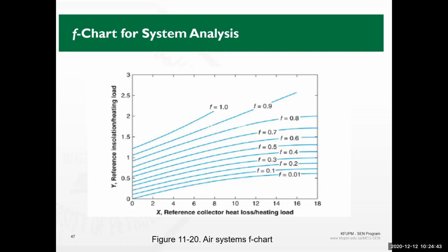But usually those collectors, what kind of maintenance usually do you have to do? Replacing maybe the modules? You do not replace the modules normally. The modules are long living. The standard lifetime for this collector is somewhere between 20 to 25 years. You may need to do cleaning every now and then, especially if you are in places where there are a lot of dust storms. And you may replace the pumps maybe every 5 years or so. If you are talking about liquid water pumps, that might need to be replaced from time to time.